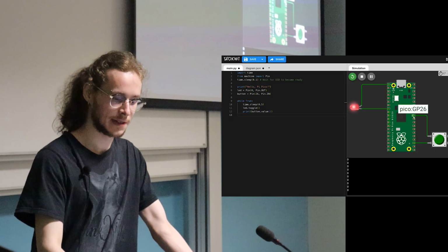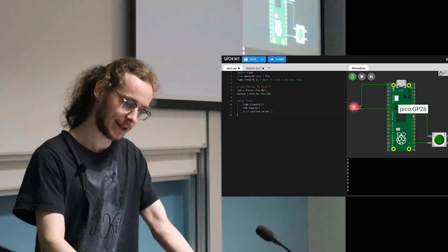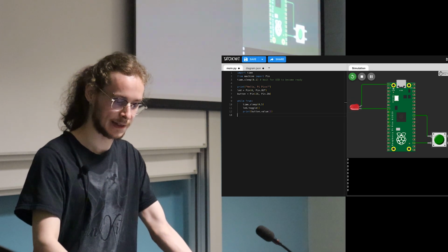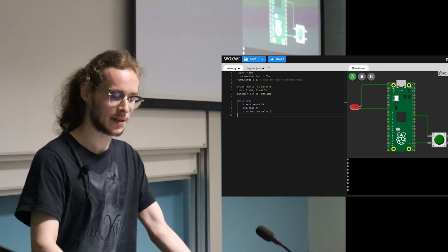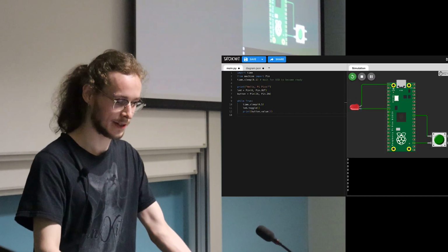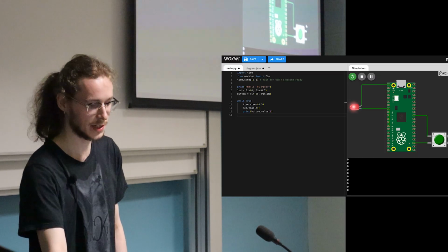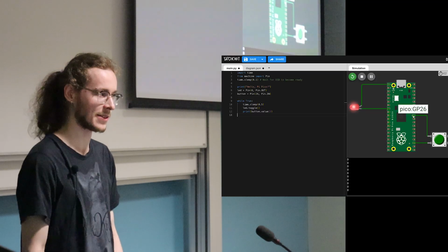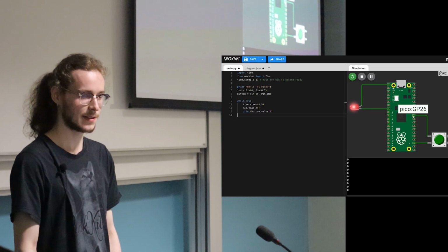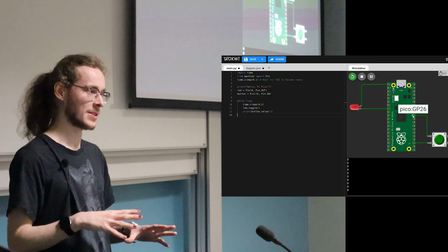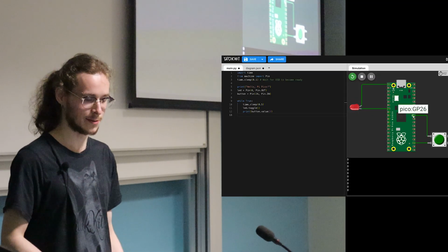You can look at this and think, well, this pin is connected to here, but it's not connected to anything else, because it's not connected to this side. So you can think of this pin as not being connected to anything. So it's working as an antenna right now. It's just receiving random noise that we don't care about.